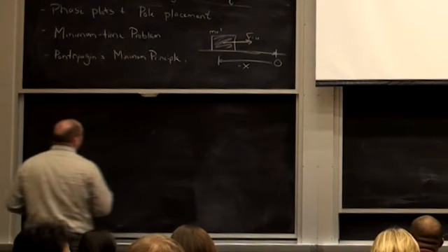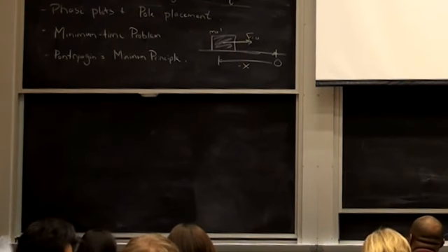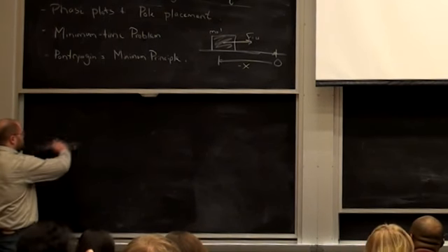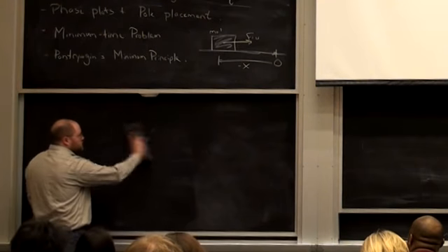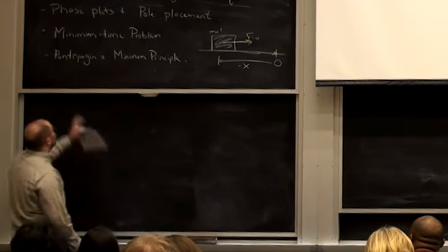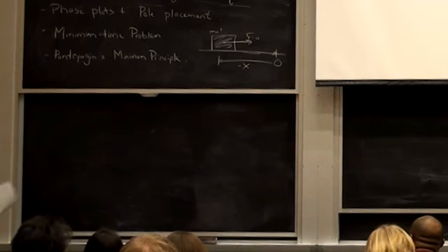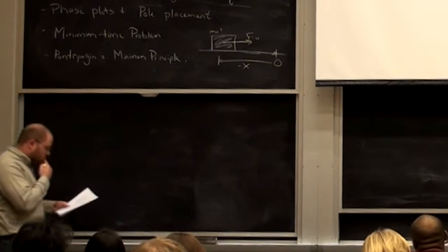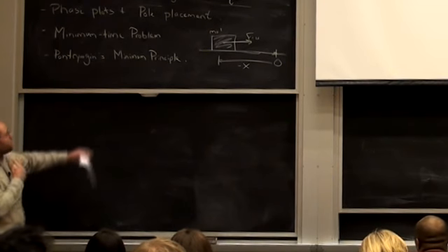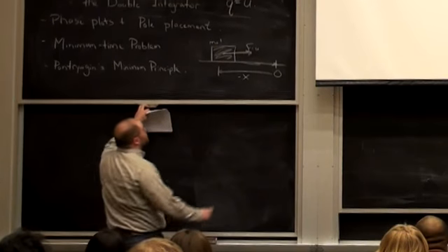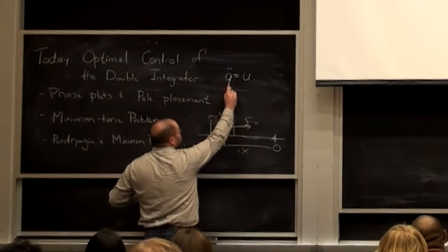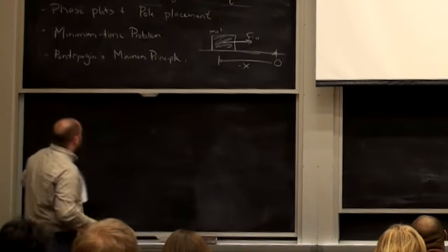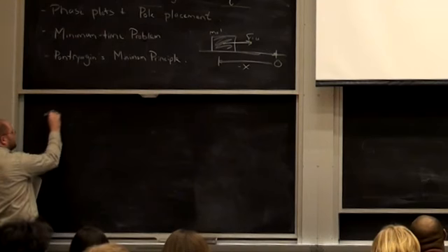Okay, so I've been trying to bring the tools from the different disciplines all together. So let me start by doing just a quick sort of pole placement analysis for those of you that don't think about poles and linear systems that much. So if I want to write a state space form of this equation, again, I've always tried to use q just to be my coordinates, and I'll use x to be a state vector. So a state space form of this.